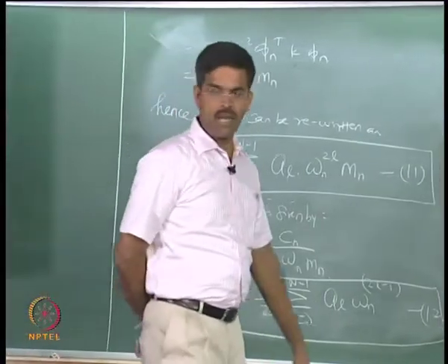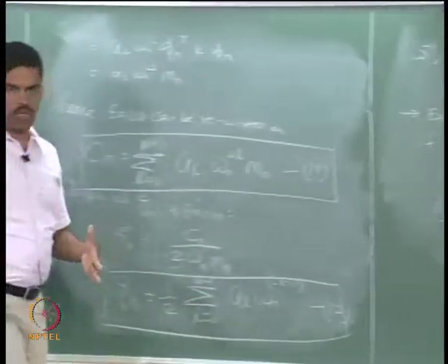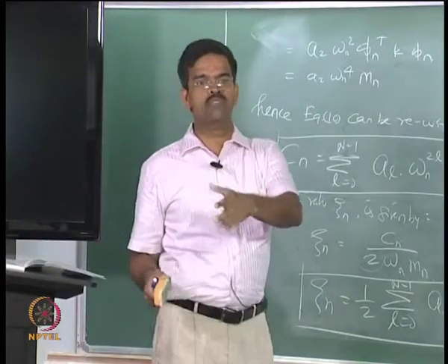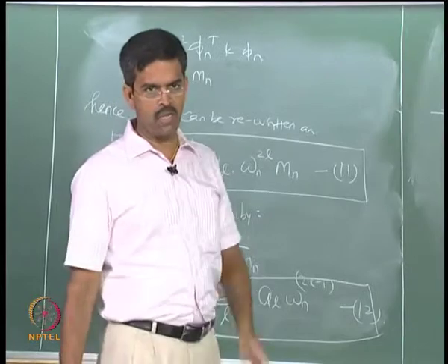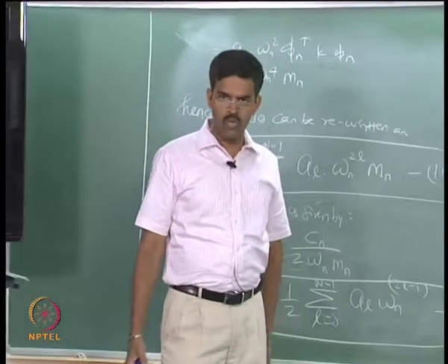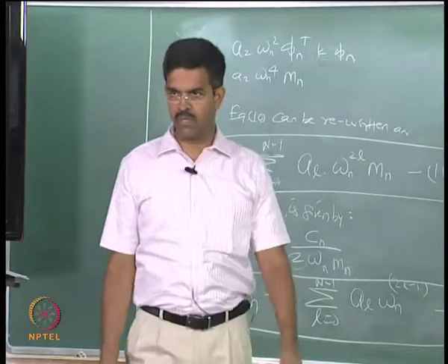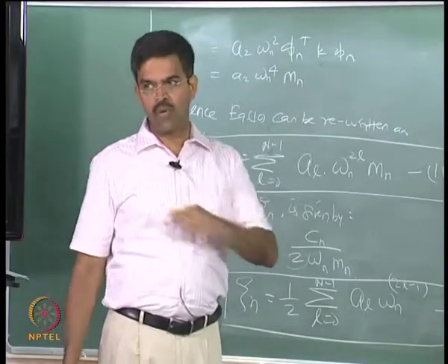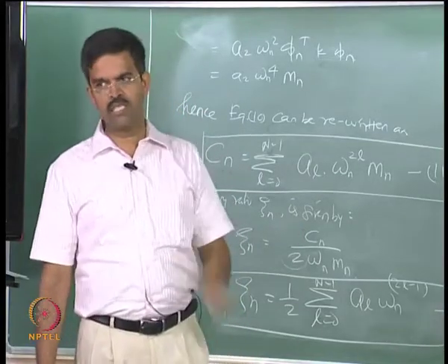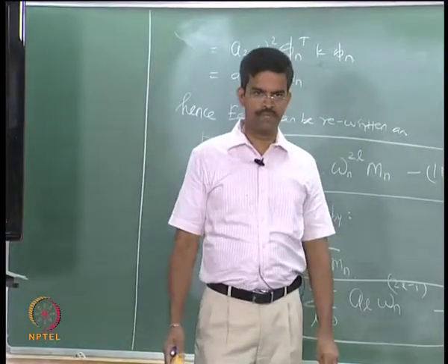So, let us pick up the same example quickly and try to solve for A_0, A_1 and A_2 and get the C matrix and see how this C is different from the last C matrix we got in the earlier lecture. They are different, is it not? Because there we got only A_0 and A_1, I picked up only two frequencies ω_1 and ω_2. I showed that ω_3 ζ_3 is approximately equal to 5, it was around 6 point something, is it not? But here I will fix zeta for all frequencies same, okay, and get the C matrix and compare how the C is different from the earlier C, okay.